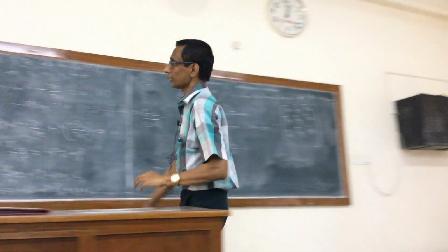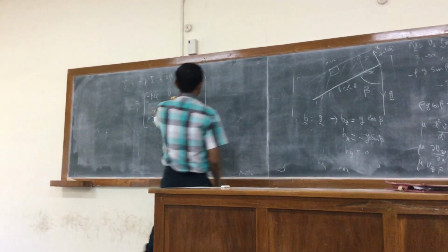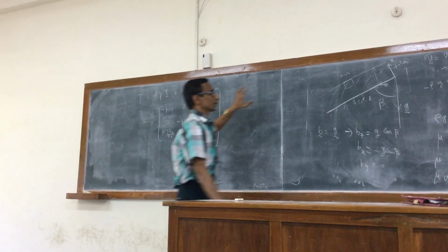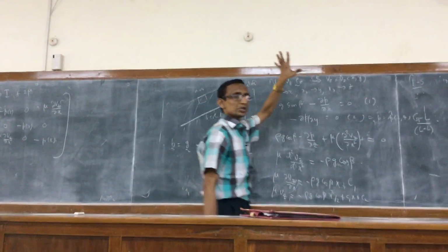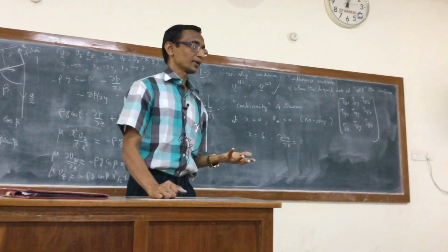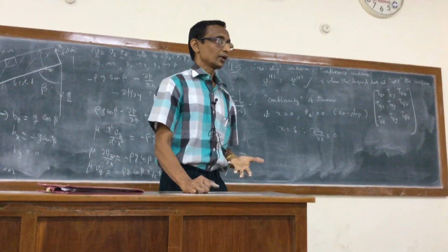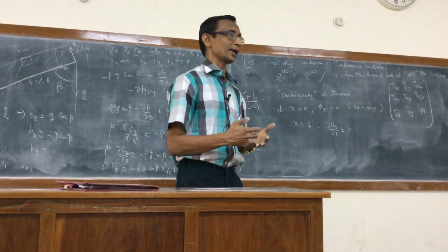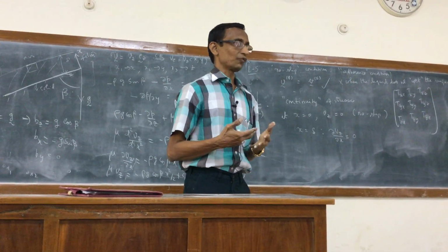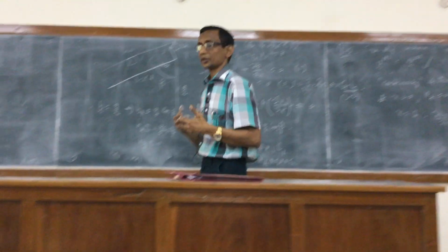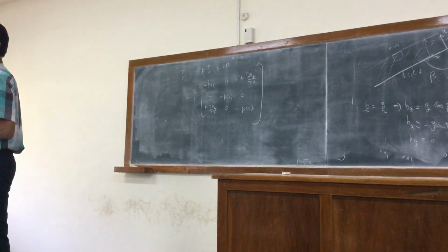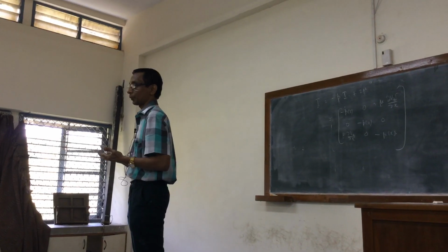So we say that the shear stress in the liquid, given by mu dvz by dx, must equal the shear stress experienced by the air, also due to the flow of the liquid. And because air is a very low viscosity fluid, we would say that the shear stress is 0 for the air. Approximately, it can be neglected.